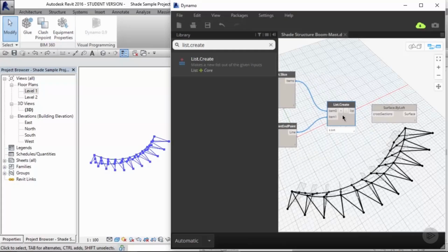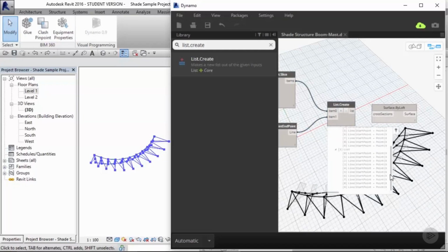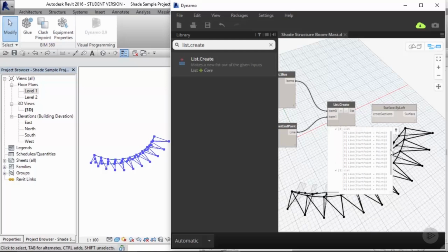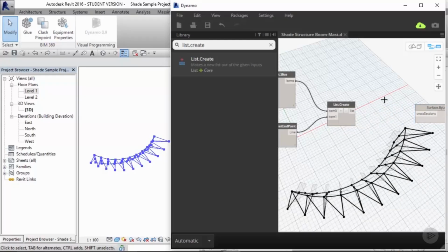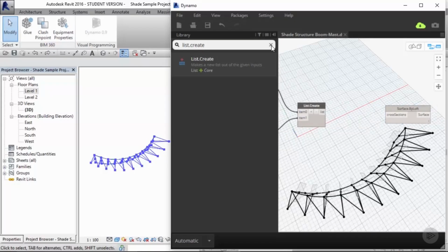What you'll find if you put a watch node on the end, or if you just hover over and look at the list below, is that your list of lists is built out of an index list 0 and an index list 1, within which 10 lines live in each. Recall the exercises we did with concatenation, when we created sentences, we were not able to concatenate our first parent list to our second parent list.